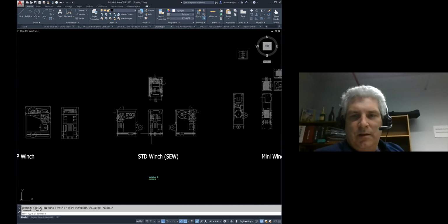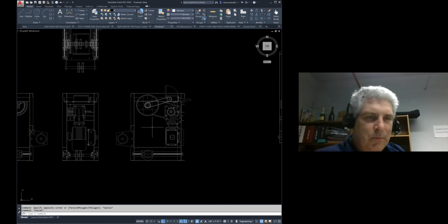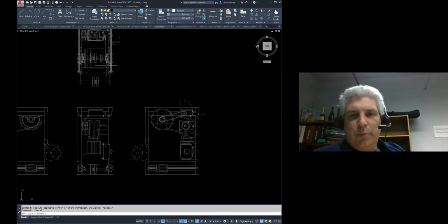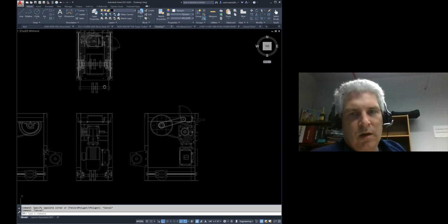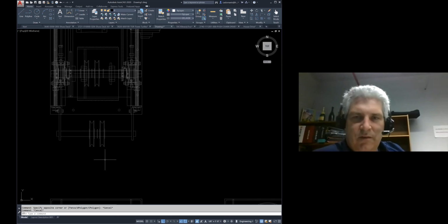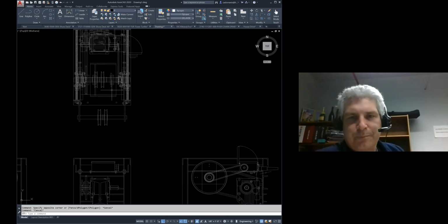And I think the last couple useful details here, and then I'll probably let Loren, I think you might be back, jump back in. But usually we're going to end up with a loop of cable coming off of this that we're going to drive. So we're going to come off one side of the drum and go out to our pallet or whatever. We're going to loop back around and bring the other end of that cable back into the drum so that we essentially have a closed loop. And the nice part of that is it means that, again, with the groove drum, every time we let a foot of cable out, we can take a foot of cable up on the other side, and we can maintain this closed loop system.